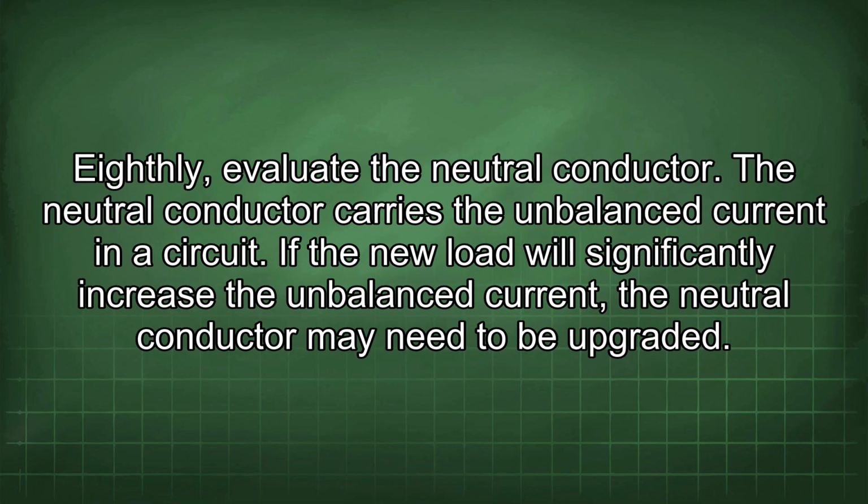Eighthly, evaluate the neutral conductor. The neutral conductor carries the unbalanced current in a circuit. If the new load will significantly increase the unbalanced current, the neutral conductor may need to be upgraded.